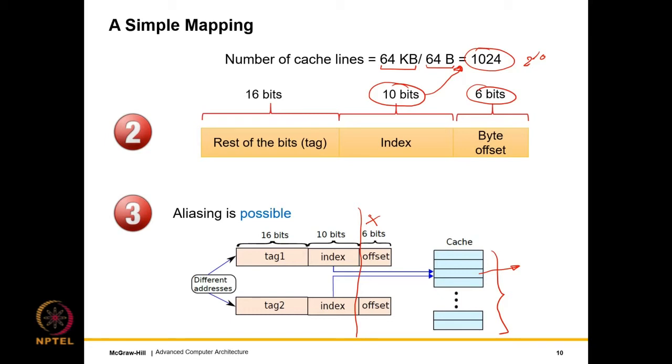In the worst case we will have a wrong prediction, and that will lead to a loss in performance, but there will be no issue in correctness. But in this case there will be an issue with correctness because we can clearly see that different addresses are mapping to the same entry. So we can use the same trick. We can have a tag.